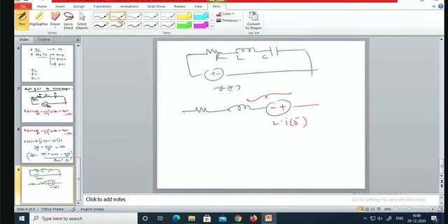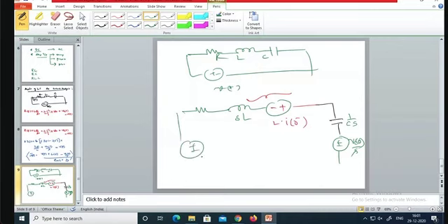And coming back to the capacitor branch, write the capacitor as it is. This inductor you write as S into L, okay? And this is 1 by CS, and you have to represent the initial condition of the capacitor like this in terms of VC of 0 by S. And complete the circuit like this, V of t. This is one part and this is another part. This represents the inductor part and this represents the capacitor part.